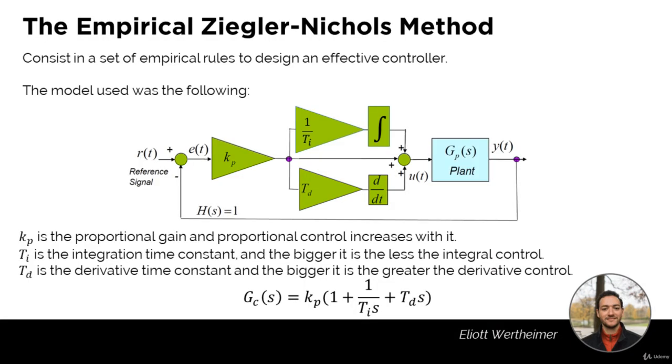Once you put proportional, integral, and derivative control together, it becomes very hard to design an effective controller using analytical methods such as the ones we used in previous lectures, when we used the second order characteristic equation s squared plus 2s times the damping coefficient times omega n plus omega n squared.